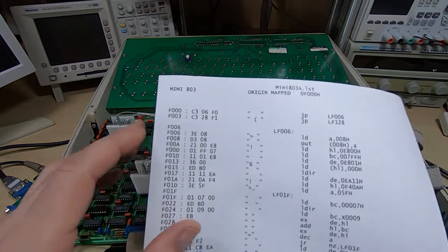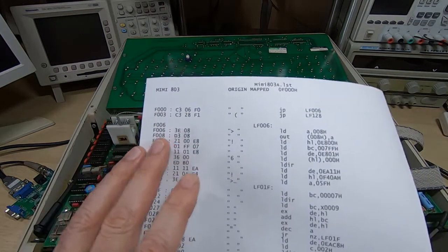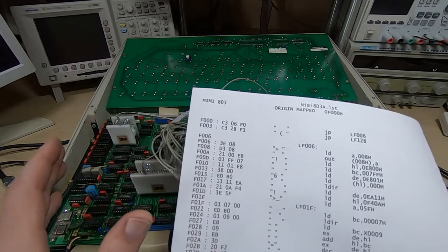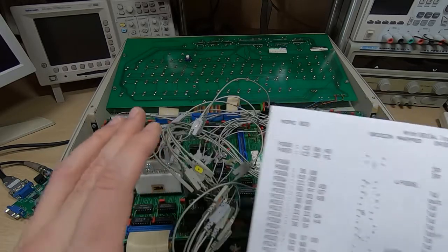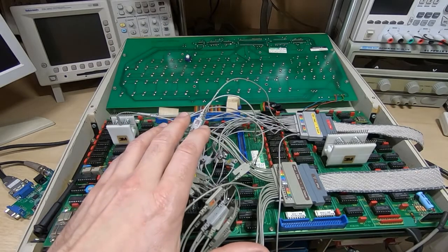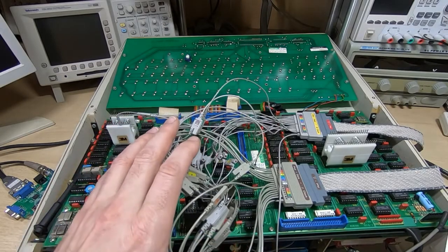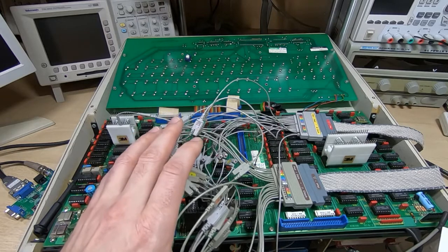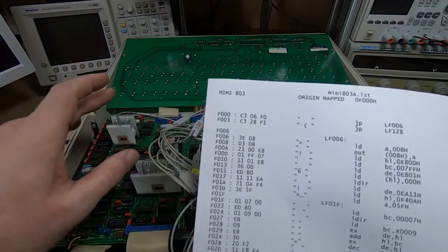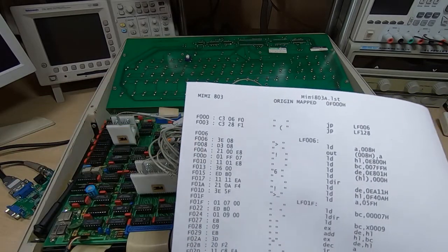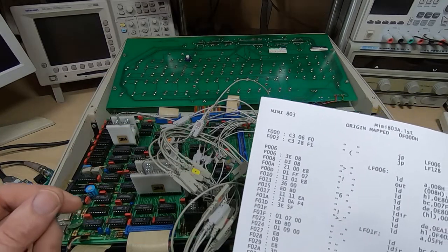but if you're interested, the general idea with most machines, and it does vary, every single machine's different, but normally, especially a machine like this that's intended to run CP/M, and CP/M needs RAM at the bottom of the address space, and that means that you can't just leave the ROM at 0000 because otherwise CP/M won't run.